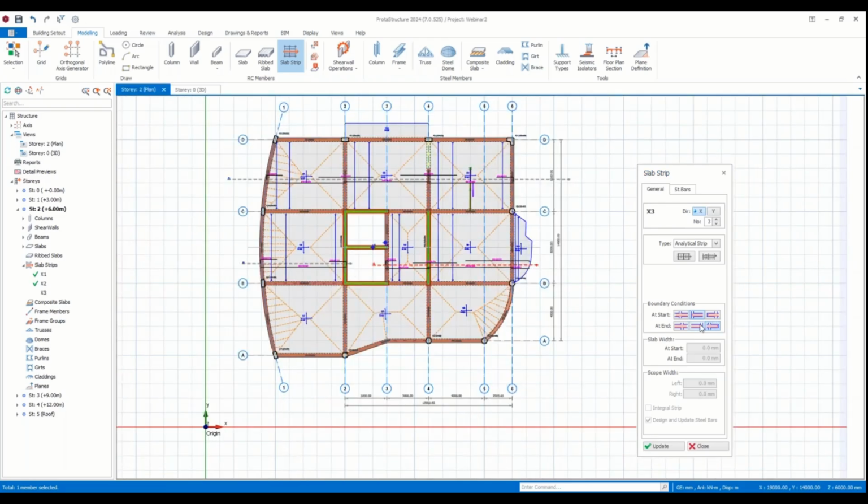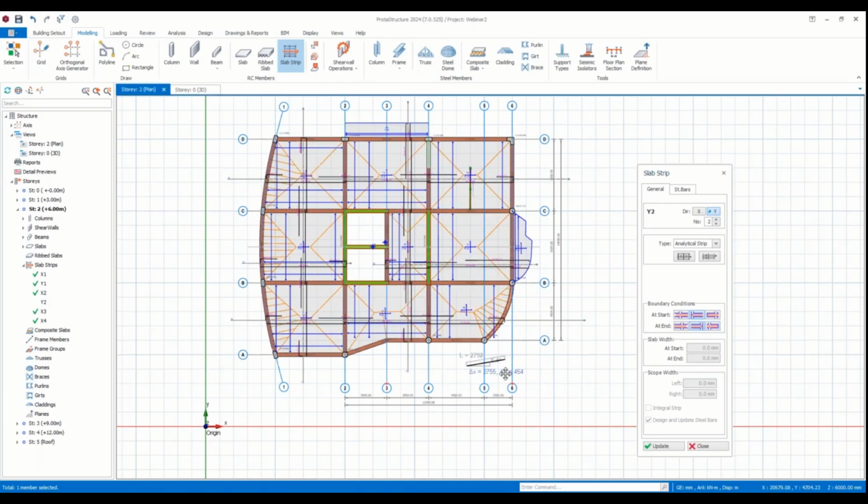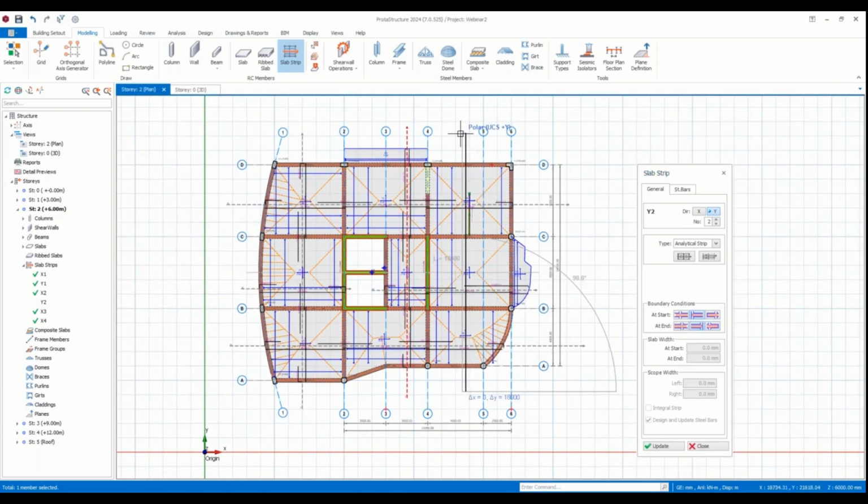Okay, and lastly, if you want, you can also add in Y direction quickly. It will not take too long. Make sure that you are selecting correct boundary conditions. Otherwise, you can see error messages like section insufficient, because sometimes clients are forgetting this option, which is for cantilever.